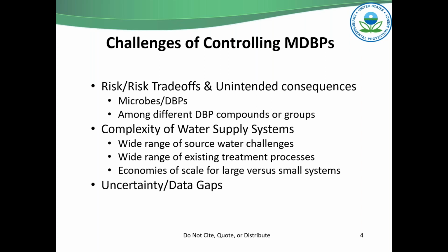The second one has become more informed with time, and that relates to if you control for one group of DBPs per, let's say, an MCL like THMs, then you have treatment responses to that create different mixtures of DBPs. So we want to be aware of those potential implications.